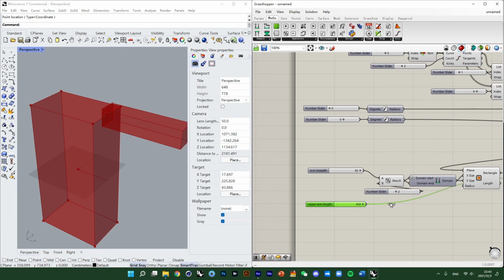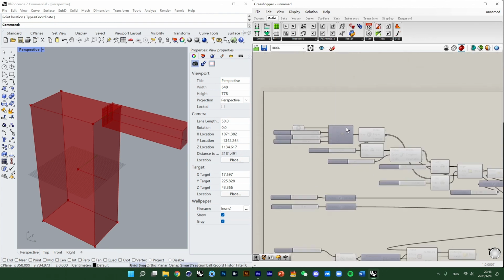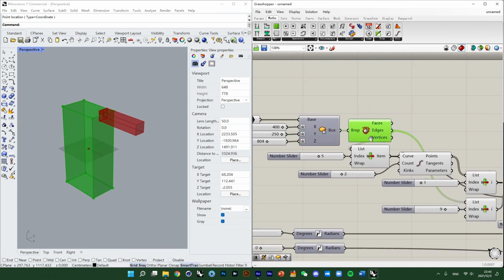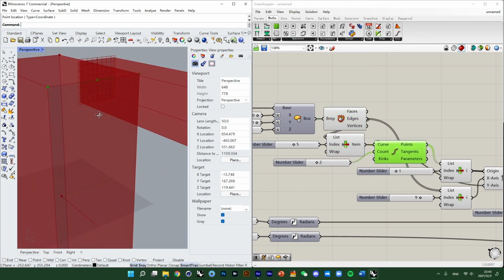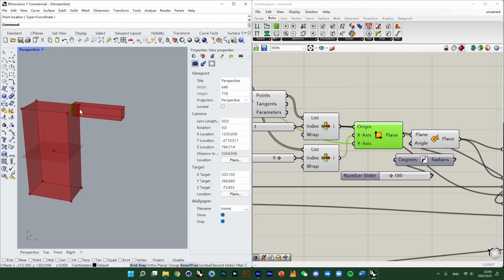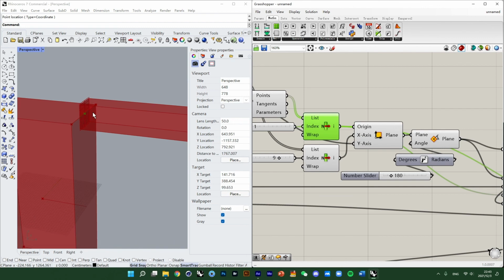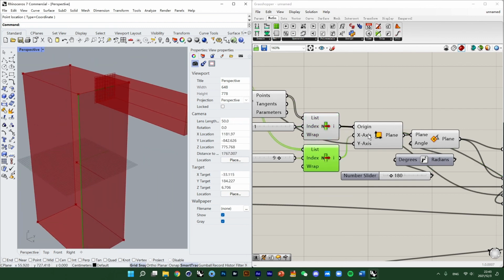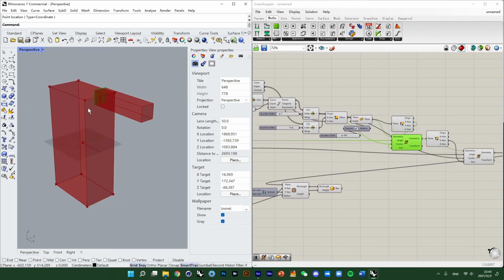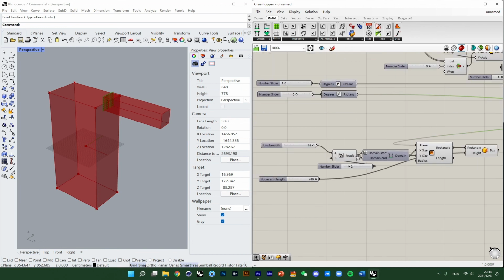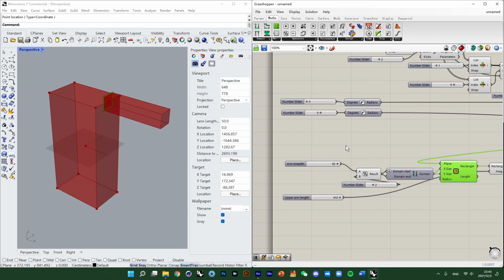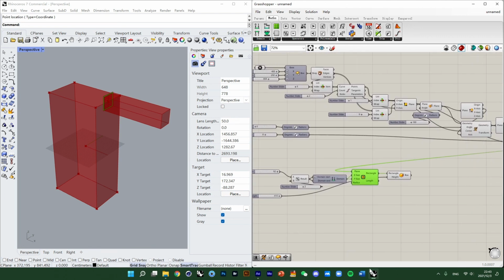In this episode, I mainly talked about how to use brep, brep deconstruct, and list item to generate a specific element of our geometry, and we learned about how to construct a plane with input of origin and the XY axis, and we learned how to construct a rotation axis for our rotation, and at last we used domain to create a centered rectangle, and in the next part we will continue to construct our arm.